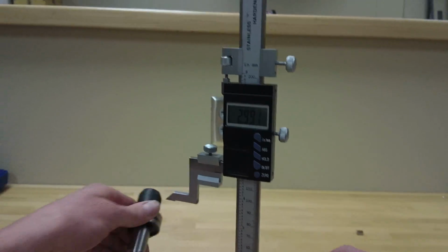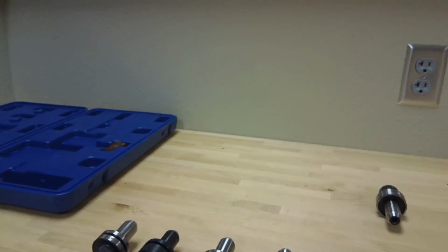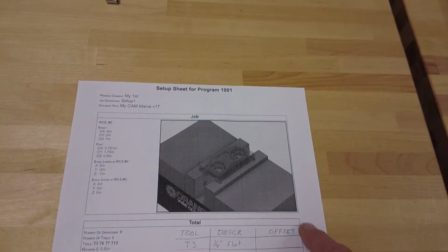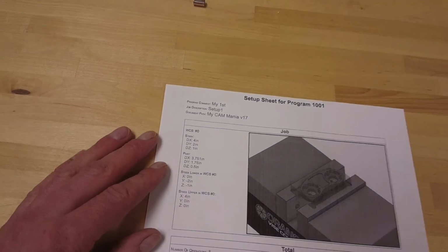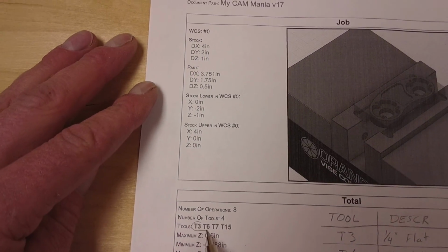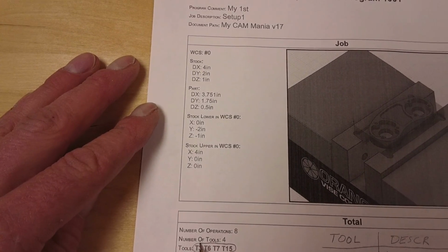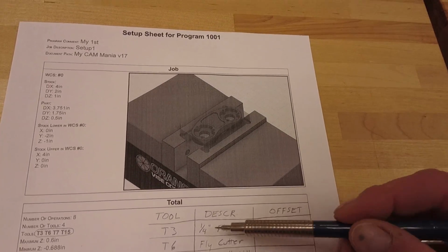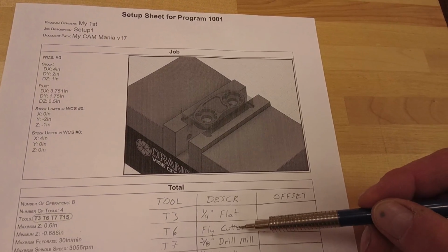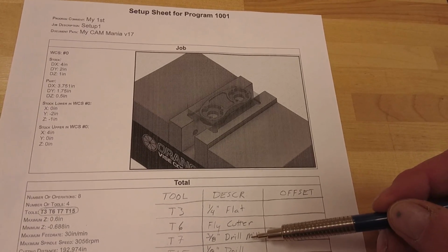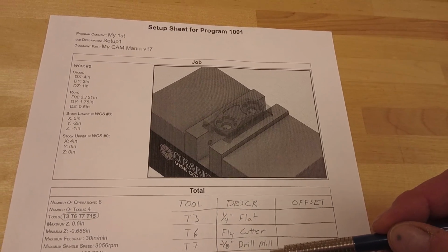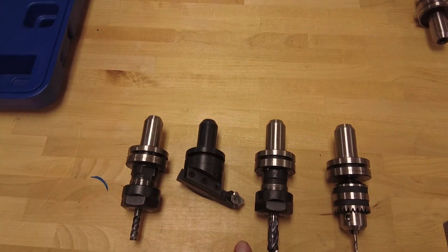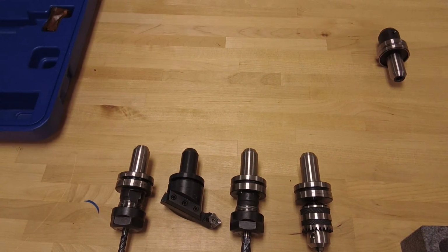And we'll bring this up, and for this sample program, we've got our setup sheet printed out here, and I added a little table to this sample sheet. We're going to be using tools number 3, 6, 7, and 15, and jotted down what each of those tools are. Tool 3 is a 1/4 inch flat. We've got the fly cutter for tool 6. T7 is our 3/8 drill mill, and then we've got an 1/8 inch drill. And so we've got all 4 of those tools over here, and we just need to record the offsets for